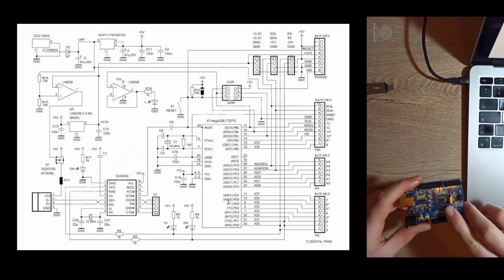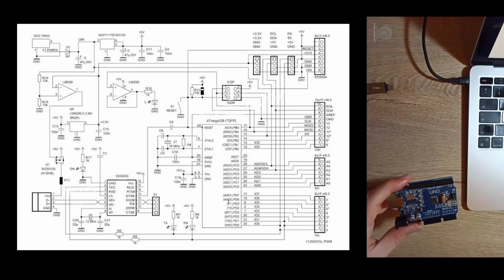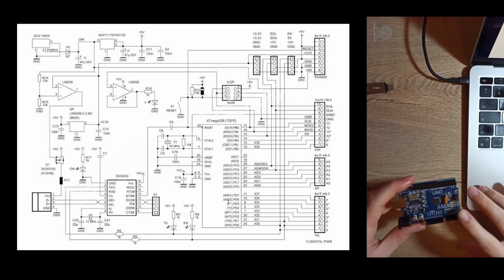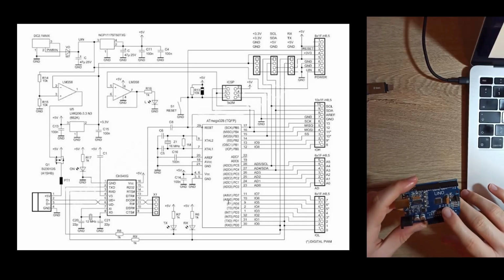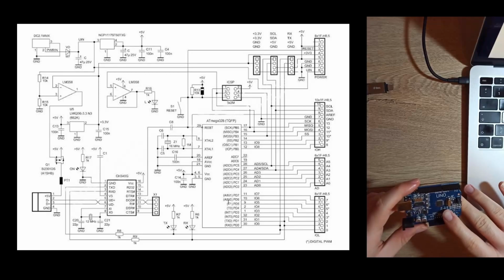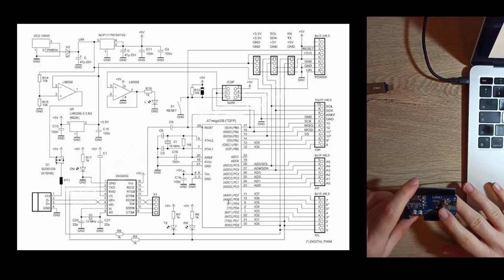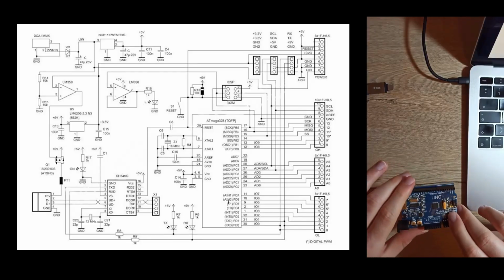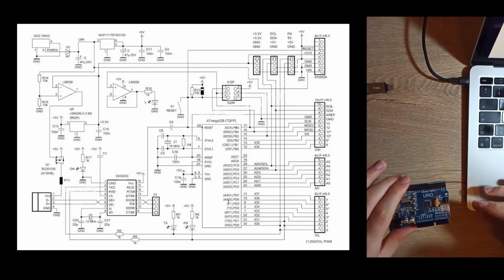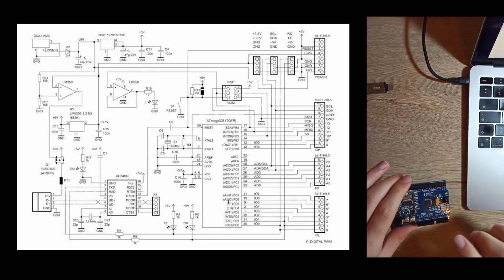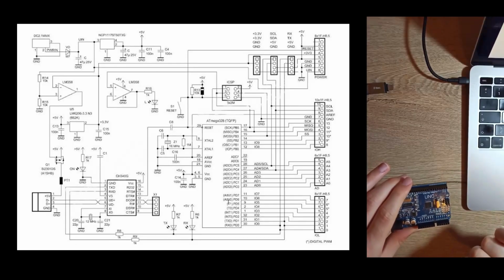So let's talk about the memory on the atmega chip. It's a microcontroller. It can do arithmetic operations, ALU operations. It can do jumps, functions, interrupts. It's got an interrupt routine too. But it does not come with a protocol for understanding UART data to understand the data coming from the UART and program itself accordingly. That's the bootloader software's job.